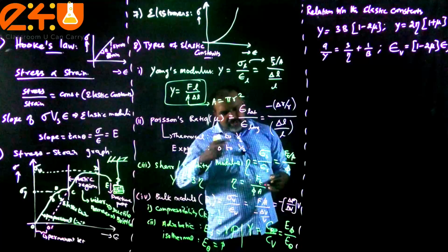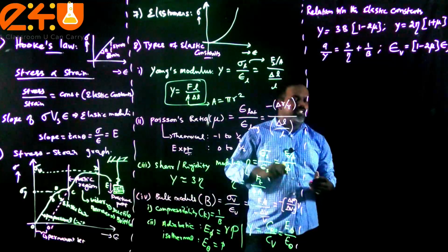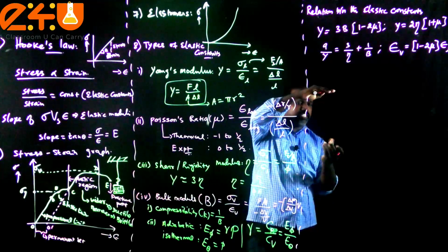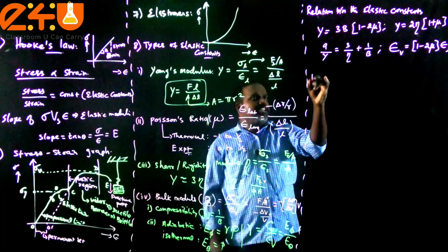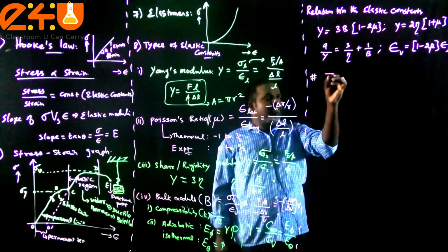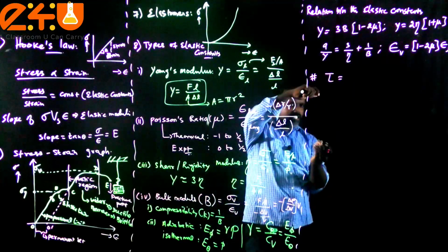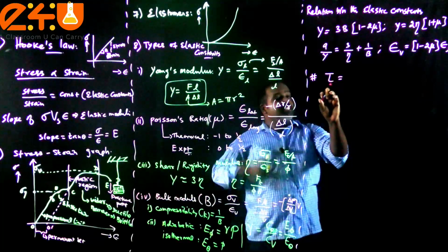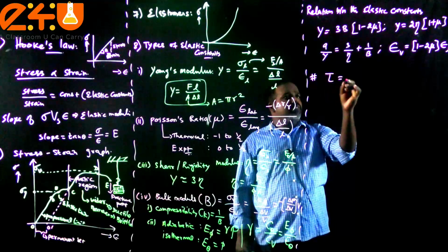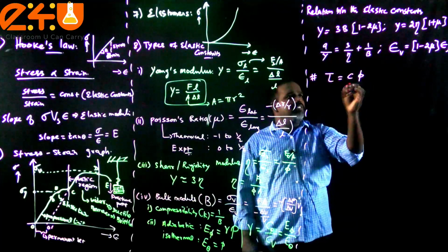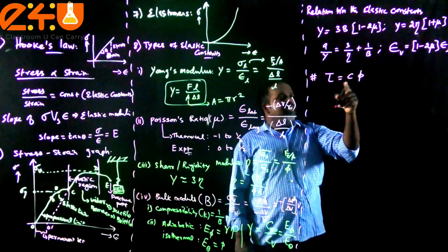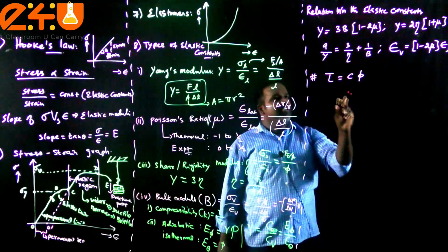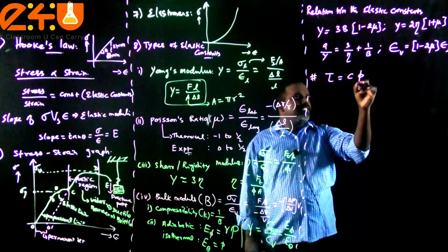And you see that when we talk about shear strain, we said that one end of the wire is fixed and the other end is rotated, twisted. In that case, the torque which acts on the cylindrical body to twist that wire is the shear torque. I can name that shear torque, equal to C into phi. This is like F equal to kx, so tau is equal to C phi, where phi is the shear angle, as we said earlier.